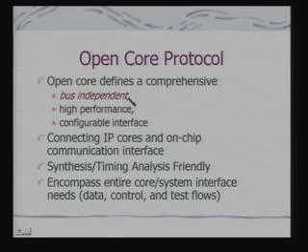And why is it bus independent? Because you will be defining the bus which is consistent with the protocol. A protocol can have a variety of transactions defined, and depending on your requirements and the device characteristics, you may define the bus. But if I pick up an IP core and say that my IP core is compatible to that open core protocol, that means it can support the transactions which are defined as part of this protocol.